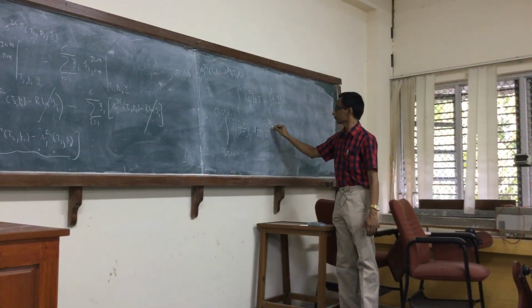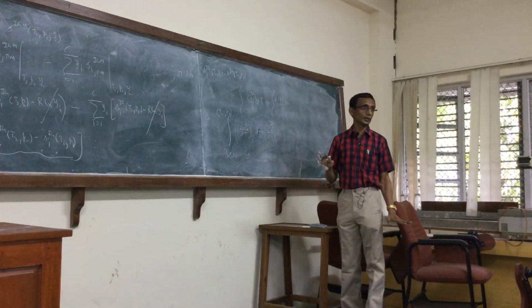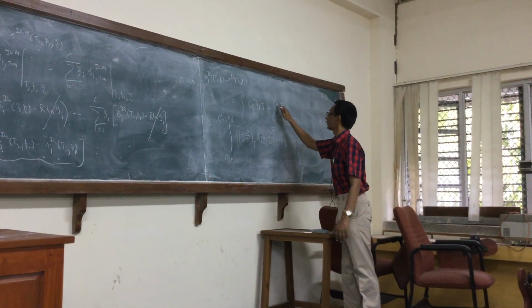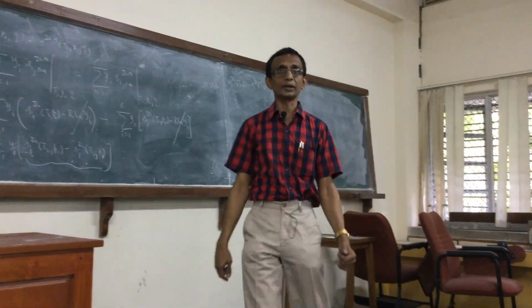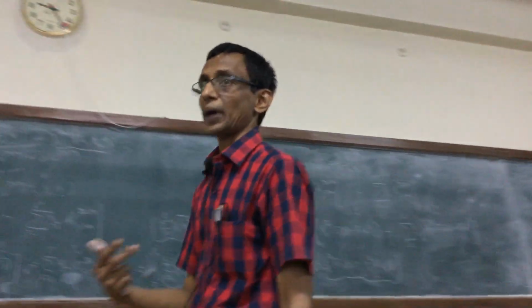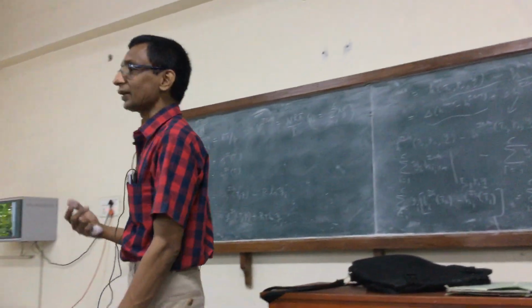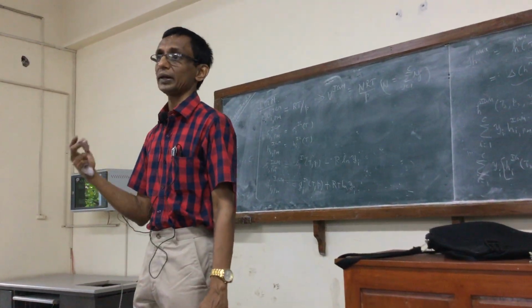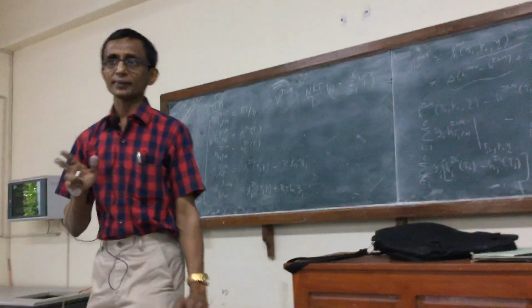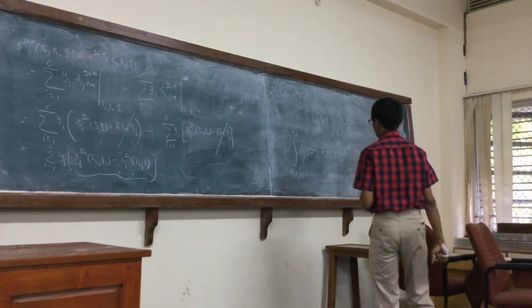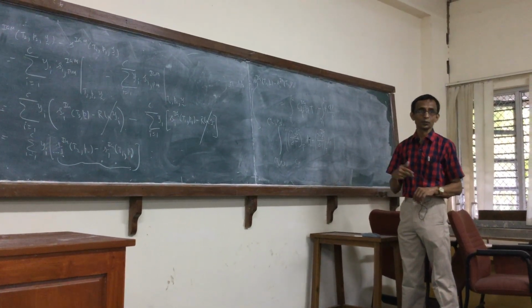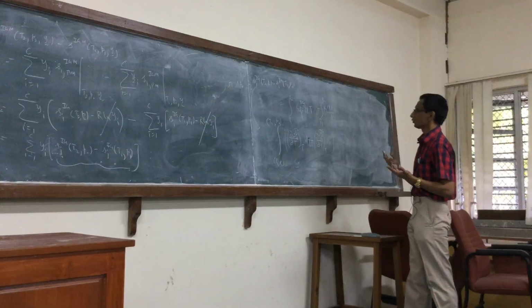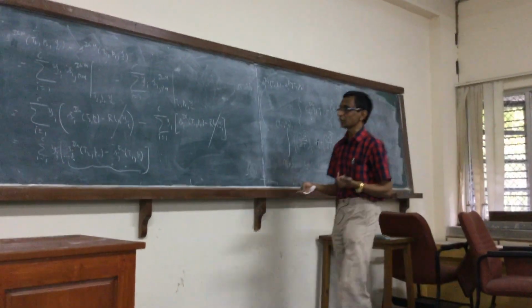What is this? This turns out to be independent of the ideal gas. So this is actually minus R over P, ds by dV, as we have seen from one of the Maxwell's relations, is actually minus dV by dT, which for the ideal gas becomes minus R. You have to understand all this and not just, the test is not to see how well you remember these formulas, but how well you can construct the steps that lead to these results.